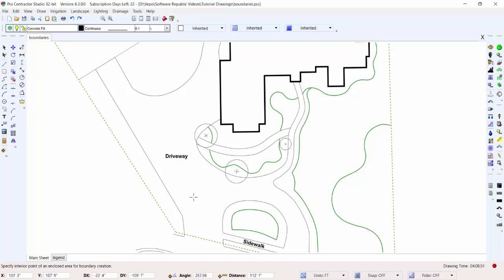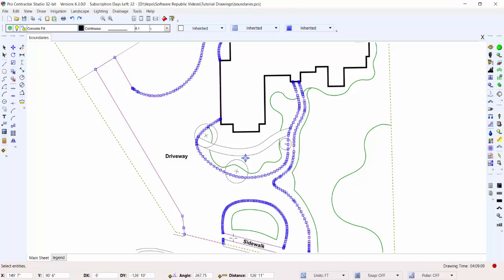Setting a point within a larger section of the area expands the search for the boundaries in large segments. When the search reaches a small section, it cannot expand into this area and will fail. By setting a point in the smaller section of the area, the search will expand in smaller segments, allowing it to find the boundaries of all areas. Searching in smaller segments will increase the search time, but will provide better results when creating a boundary.